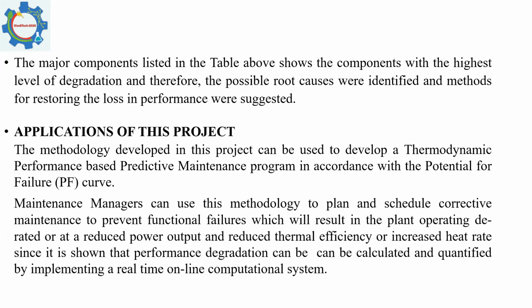So this basically is the basis of this project, and as I said, in relation to process parameters, operating parameters usually is what most plant operators use as a guide, and sometimes it may be misleading for many reasons. There's a particular case, for instance, on a gas turbine where on a hot day, the compressor performance is affected because of the higher ambient temperature of air. And we cannot basically use that as a guide to determine its performance.